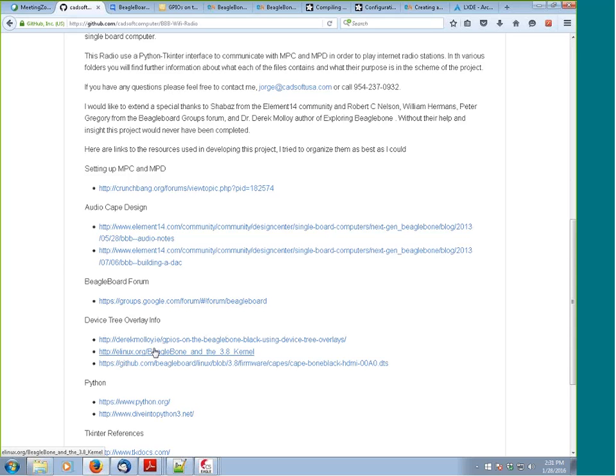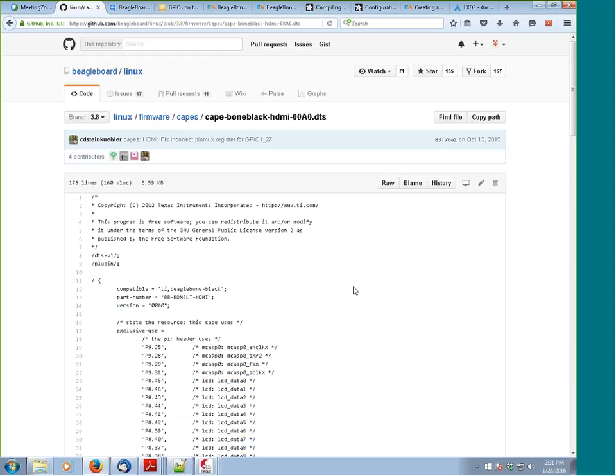So what happened? When I hook up the screen to the Beaglebone Black, the screen uses the HDMI video output. Okay, so it takes ownership of that. The problem is that when it takes ownership of the video, it also disables the HDMI audio because all of that is together. In my case, my Shield requires that HDMI audio. So when I plug in the screen, I automatically lose the functionality I need to be able to get audio out. And this actually became a very, very long process. I spent, I think, a good 3 weeks dealing with this.